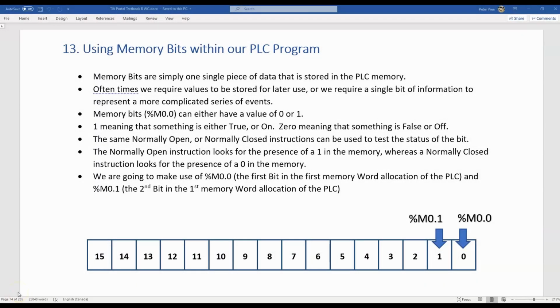Okay, so in the previous video, we found that the PLC SIM was awesome, but it doesn't allow us to modify physical input bits, right? Things that exist in the real world. So what we're going to do is I'm going to introduce a new topic, memory bits. In this case, we're going to change our inputs to %M0.0 and %M0.1. So instead of looking at physical inputs that exist in the real world, we're just going to look at memory bits, little bits of information that are within the memory of the PLC.